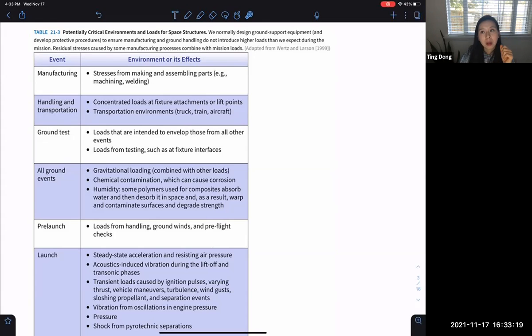And also, I was an aircraft structure engineer before I came to UF. From what I have seen, the major problems of aircraft structure failure were corrosion and widespread fatigue cracks. For the cracks, the majority originated around the fastener holes.